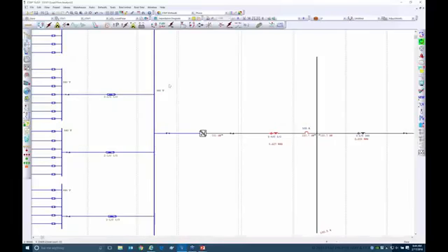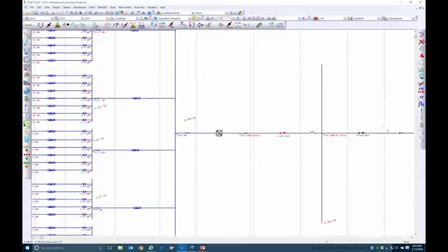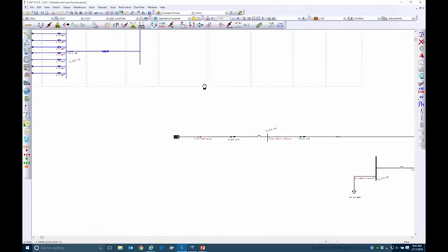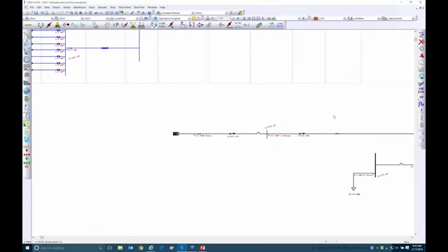This is one way of doing it, but we've introduced another type of calculation inside ETAP, which allows us to do a complete AC and DC simulation in one shot. So you can see my DC power and my AC power injection into the grid in one single calculation, without having to go back and forth and iteratively solve the AC side and the DC side. Obviously, if you're not interested in the details of what's happening on the DC network, you don't really need to model it in this fidelity. You can just look at an AC-only equivalent circuit.